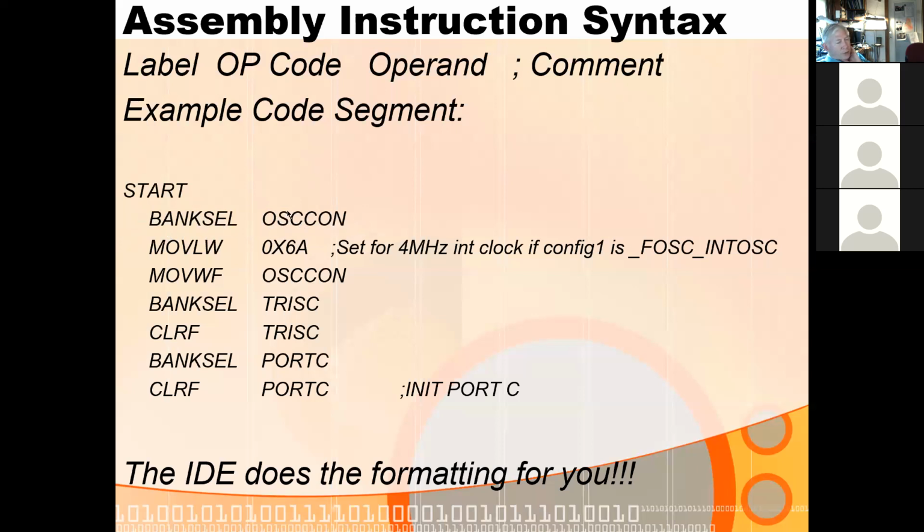What banksel does, remember I said you as the programmer have to make sure you have the right information. You have the upper 5 bits of the address in the bank select register. Well, this banksel instruction, and then you tell it what variable you want to be correctly located by in the bank setting, and that's how you do it.